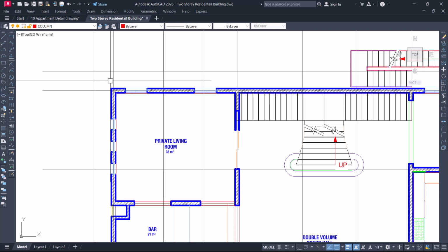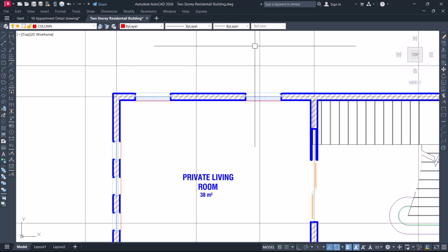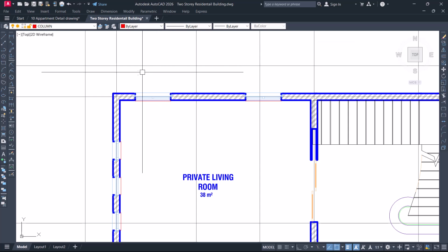Now, to place your column point, it is required that the minimum column section is 225 by 225 millimeter. For those that understand inches, it simply means 9 inches by 9 inches. Now, if you want to use a lower column size, let me say based on a 6 inches block wall, and you want to use a 6 inches column size, what you do is to use 6 inches by 450 or 6 inches by 350 at minimum. Okay, that's fine, but it's advisable to have your column 9 inch.